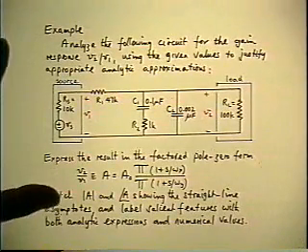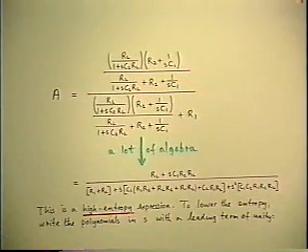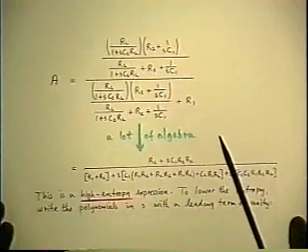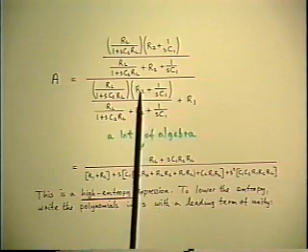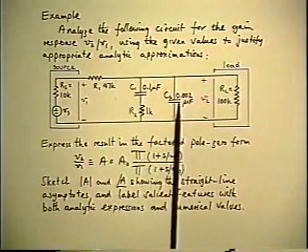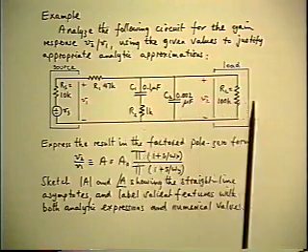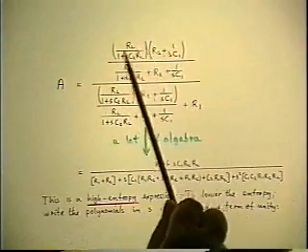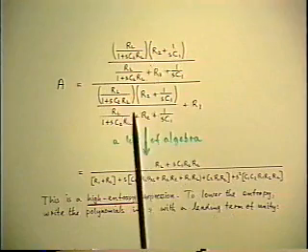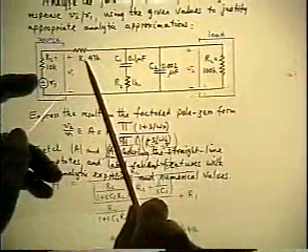Okay, so what happens is, a week later, they show up, turn in the problems, which are usually multiple pages, and the starting point is a huge equation, which you get by treating this as a giant impedance divider, where the bottom branch is all these three branches in parallel, which is what all this mess is on the top. This is the parallel combination of those three branches, and the denominator is the same thing all over again, plus the series branch, which is R1.